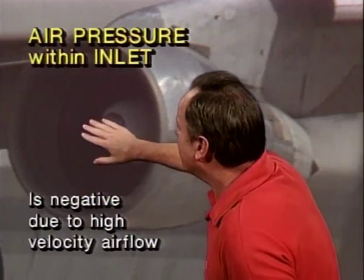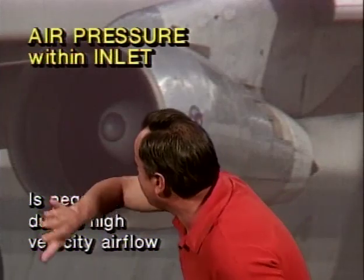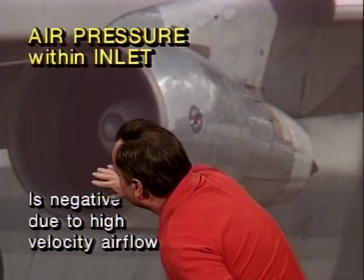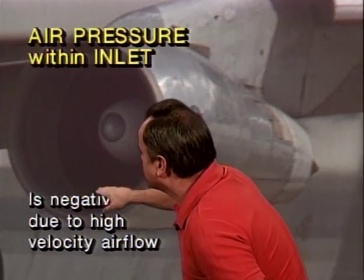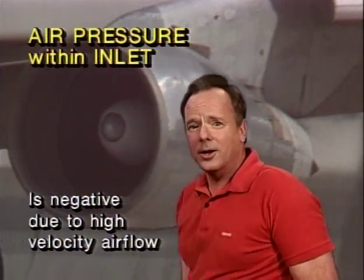And the answer is it is negative, due to high velocity of airflow being taken into that engine. And so therefore you have very low air pressure here, and they call that negative. It's less than ambient due to that high velocity airflow. So a lot of air going into the engine.